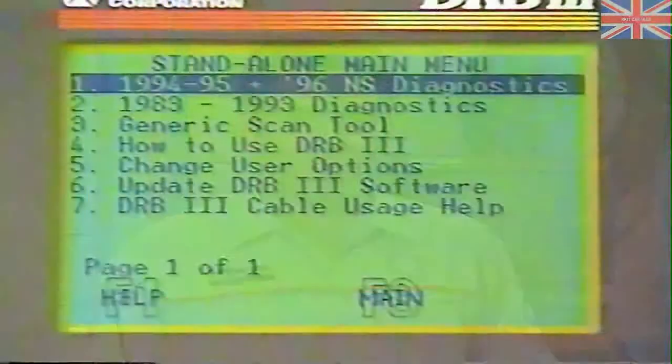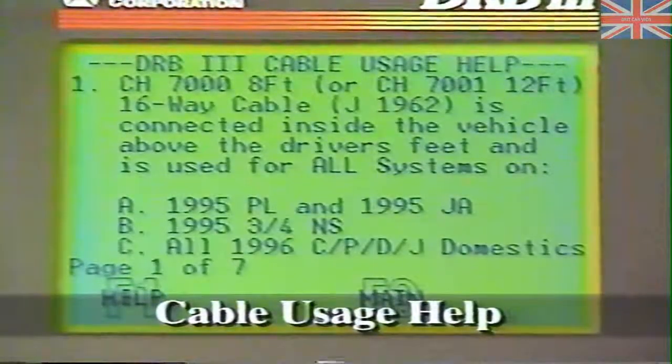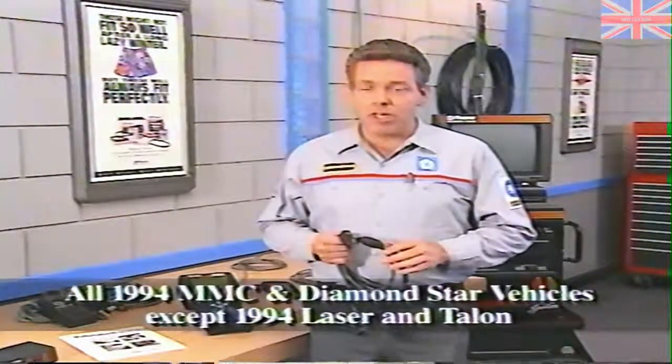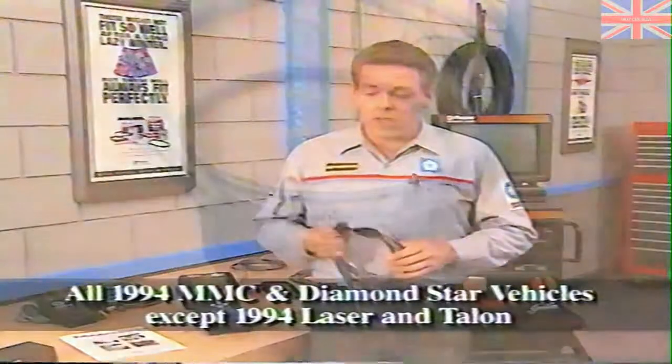Now let's go to the standalone main menu. A new addition to this menu is Cable Usage Help. This will aid technicians by giving the correct cable number for the vehicle and system to be diagnosed. Keep in mind that all 1994 and later MMC and Diamond Star vehicles, except 94 Laser and Talon, use the double-headed connectors.